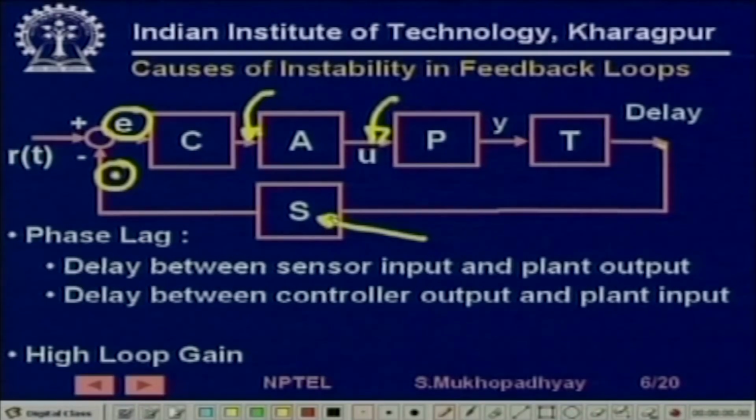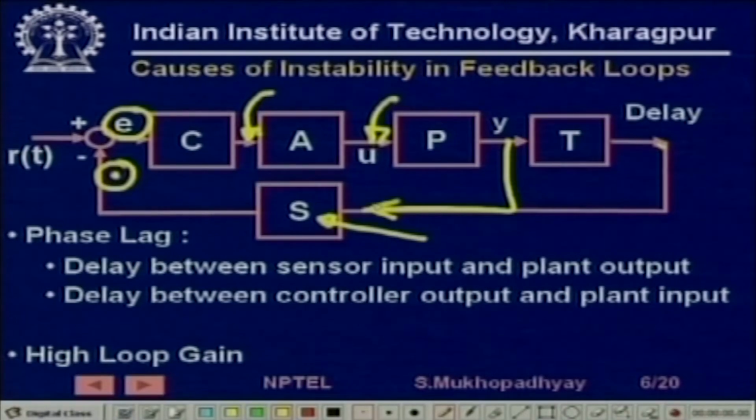You know, sometimes in automatic control processes, even sensors like online analyzers, there could be a considerable delay. This delay actually occurs in the sensor, it is not in sensing the input, directly from here it is fed, but this unit causes a time delay, that is also possible. So, anywhere around this loop if you have delay, it is a potential cause of instability.